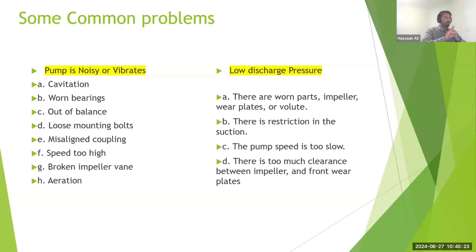One of the last parts of your questions was, how do we select the pump for a different application? The selection of the pump is primarily based upon what type of fluid you are pumping, what is the viscosity or the specific gravity of that fluid. If it's too viscous, you may need a multi-stage pump. That means it does not have one impeller, it has 2 or 3 impellers. Because one impeller can only impart certain energy. But if you have multiple impellers, then you can actually use it as something in series. You don't have to increase your pump size too much. You can actually have a pump which is more cylindrical.